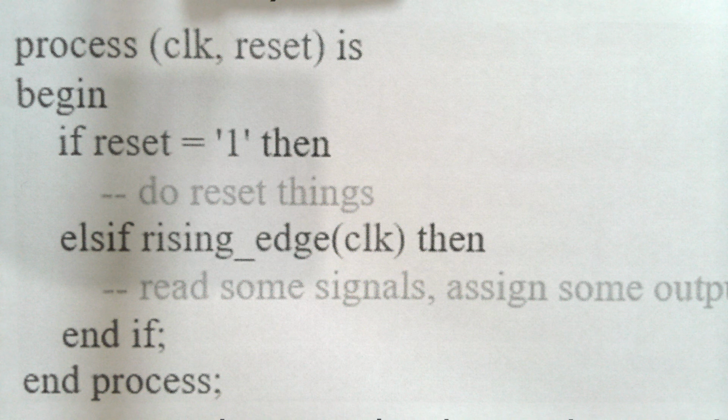So just to remind you, we needed to put reset in the sensitivity list because, unlike the previous example, it's not synchronized with the clock. It's an asynchronous reset. So therefore, the process would have to be notified of changes to it,